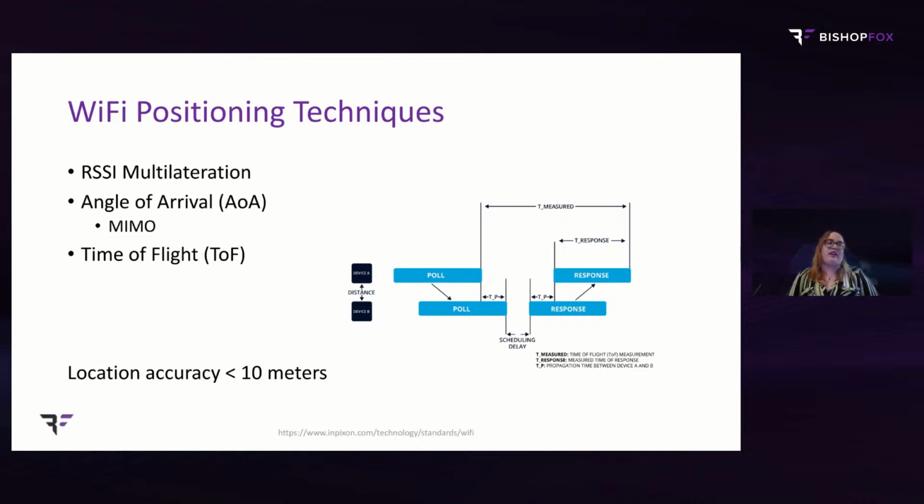So that's able to be used, but there are a couple more efficient ways or more accurate ways, like angle of arrival, which refers to the direction in which a received signal was transmitted. So by using an antenna array, the direction of the incoming signal can be determined, allowing for trilateration of the signal's source position. So an example would be determining the direction of an incoming aircraft, right?